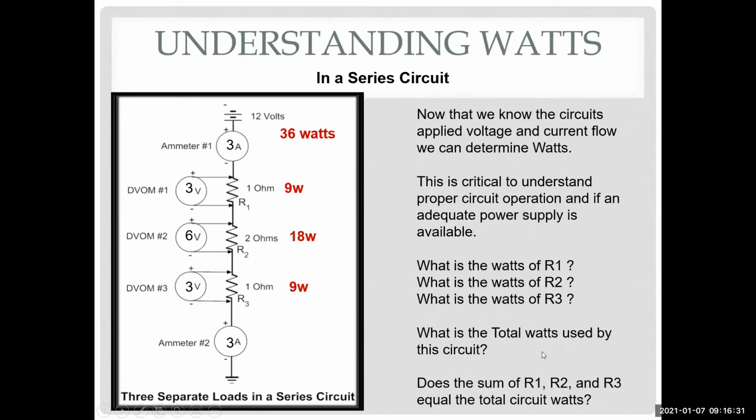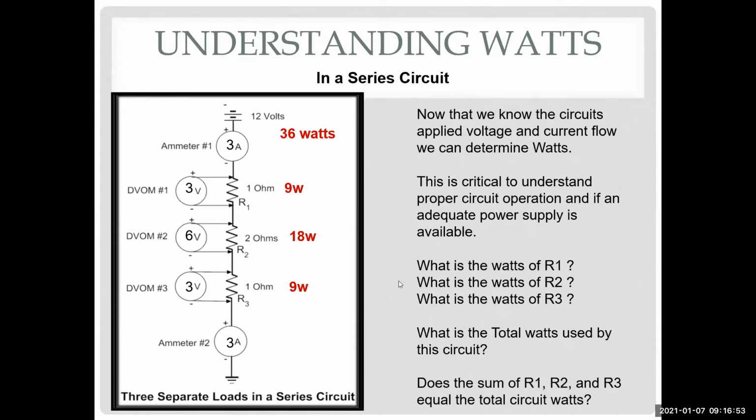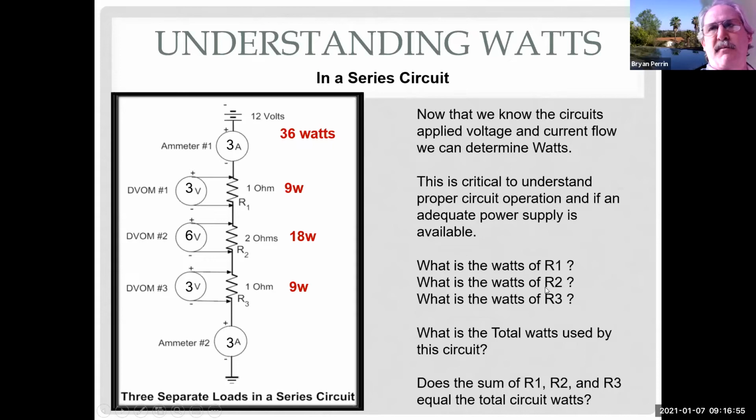But we're just gonna work with voltage, ohms, and resistance, right? Or we're gonna use watts? We use watts because I use watts in the starter module, so we'll see watts a couple times. If you get into hybrids at all, hybrids use a lot of watts, both on their scan tool data and other stuff because of how they're measuring power and torque.